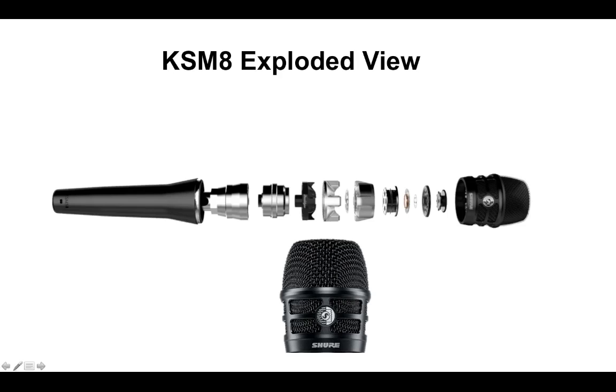So the grill is lined with a hydrophobic woven cloth. And it reduces plosives very, very well. It takes up virtually no space. There's a tiny little piece of foam in the top just for manufacturability of it. But it's glued to the inside, and it basically makes the grill and microphone waterproof. We don't have any sort of IPX certification or rating on it, but we put it under a shower head for 30 minutes. We shook it off. We ran it in the anechoic chamber, and it was totally fine.